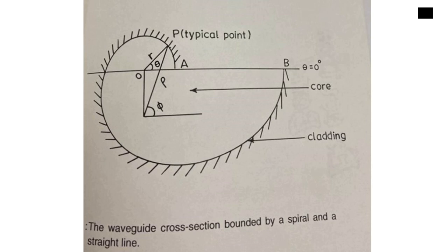The very well known scalar wave equation is del squared psi minus n squared upon c squared del 2 psi upon del t squared equals 0. And you know del squared is the scalar Laplacian operator in the cylindrical polar coordinate system r, theta, z, where n is the refractive index of the core material and psi is any orthogonal Cartesian component of the electric or magnetic field for the core region. Now, for our proposed waveguide, the solution of the scalar wave equation can be expressed as a series expansion of the solution of the fields in the circular fiber.